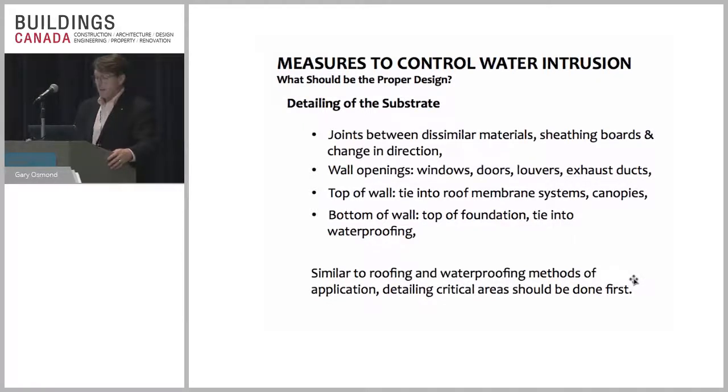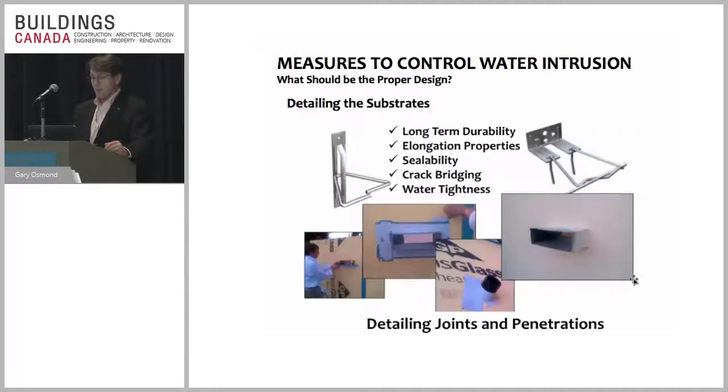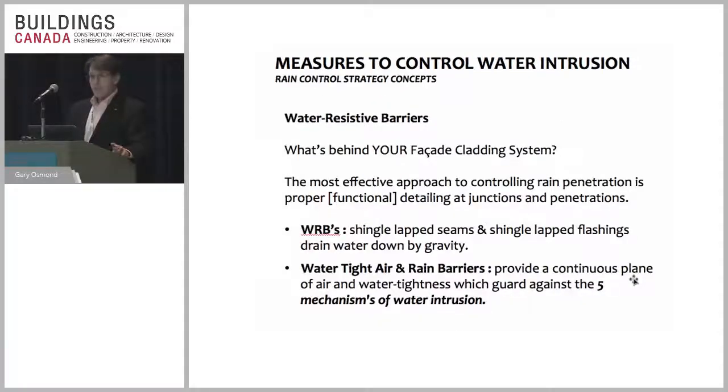grade for us. And my comment here is, similar to roofing and waterproofing, when you're putting a system on, it's about detailing first, and then you do your field applications next. Why? Well, because we stick a lot of holes in it. And have you used the right materials that will seal or fasten around all these things in order to give us that water tightness and resistance to penetrations? This isn't about air barriers, but I'm going to talk a little bit about that type of stuff.